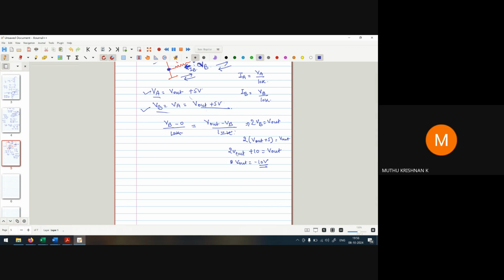And sir, what's the reason we have this battery source in the loop? That is only for providing the input voltage. So in place of input voltage, I just provide the battery in a feedback path for biasing purposes. And why do we need bias here? We need a bias because if we are not providing the biasing, both terminals are connected to the ground. So if the input voltage is ground in all scenarios, what are we getting as the output?